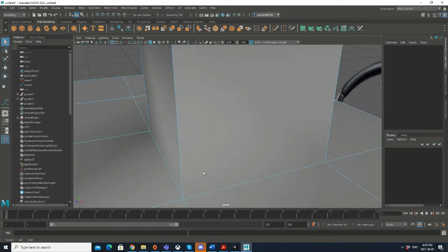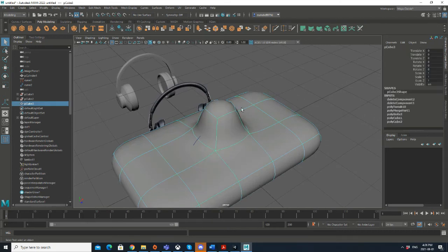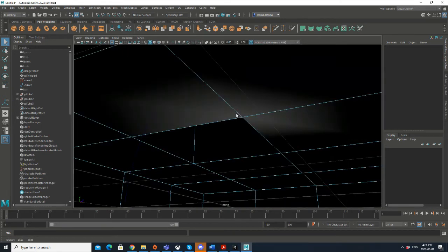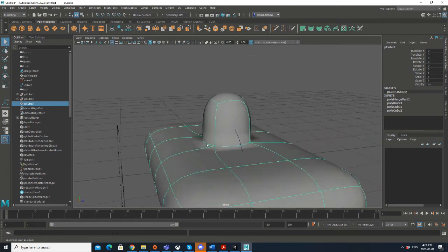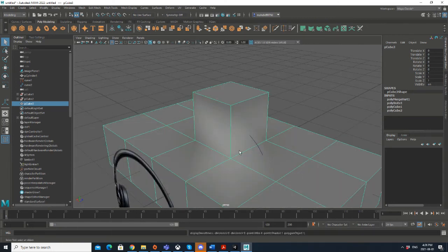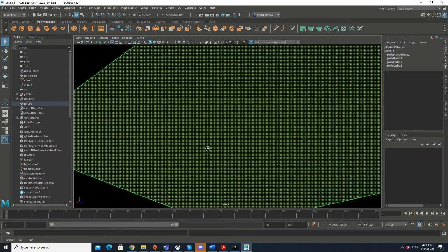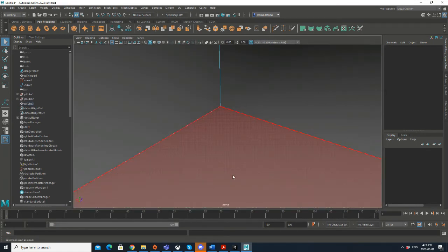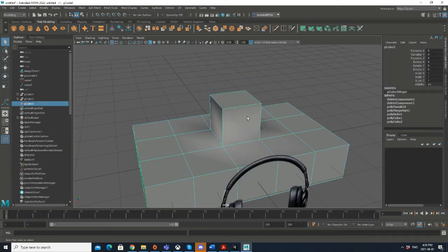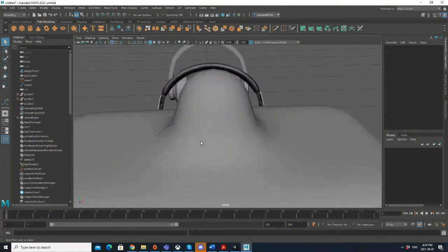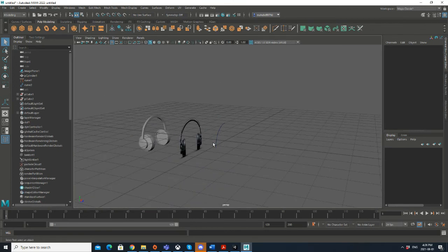So you can just delete these faces, and by going to the smooth mode you can see it's a lot better. But let's go back to the time that we haven't deleted the faces, and do the smooth thing. You can see that these parts are a lot worse, but let me go back and make it smoother. It seems a lot better. So make sure that you don't leave any face in your model. That's also one mistake that could be made.